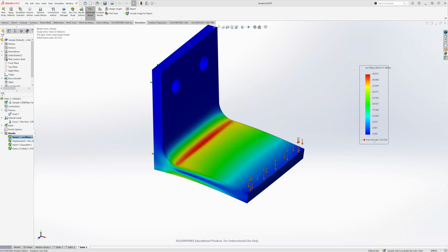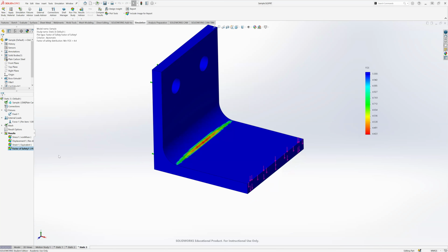It knows what the yield strength is if you have a material that has a defined yield strength. At every element or every node, it will literally take your actual stress and divide it by the yield strength at every point. Based on that, it'll get a value, and that value is your factor of safety at every point, if that makes sense. Hopefully that answers your question?